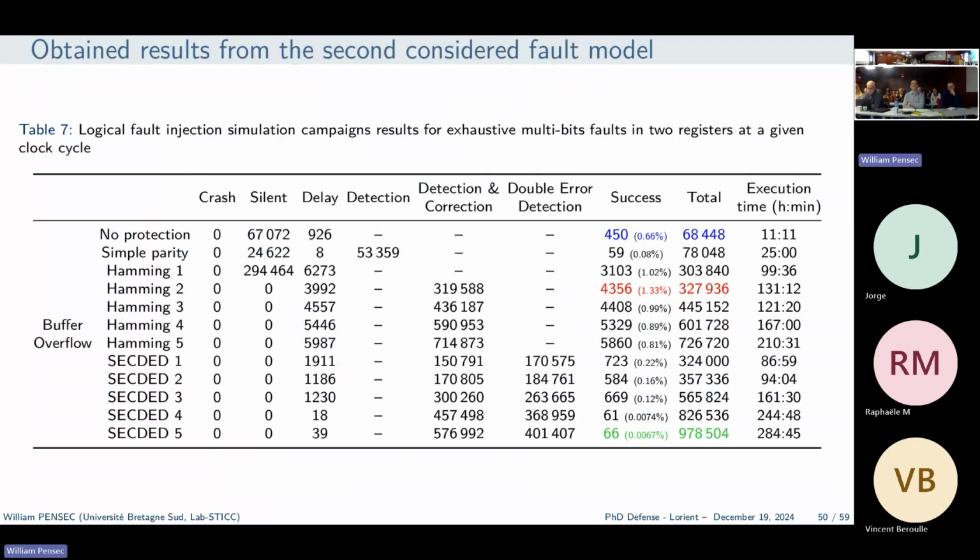No, because in this fault model, I'm considering injecting up to 11 bit flips at the same time. And because the code is able to detect and correct one single bit fault, it will detect the fault and try to correct it, but as I said, there may be 11 faults at the same time, so it will inject a 12th fault and provide another opportunity to have another success. Yes. So this implementation of the code is good, but not against more than 1 fault. Yes. So the code, in fact, gets confused.